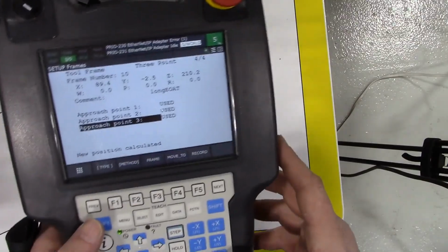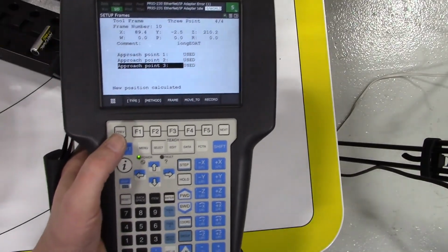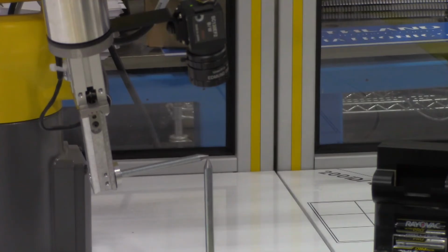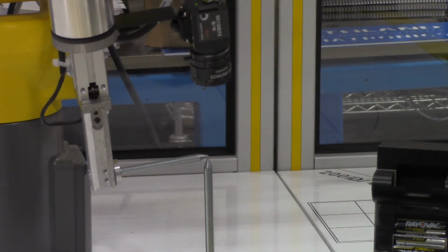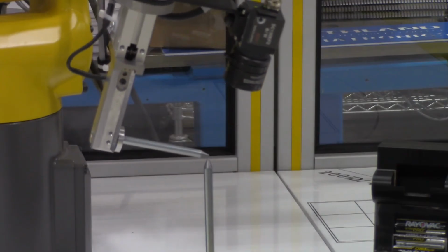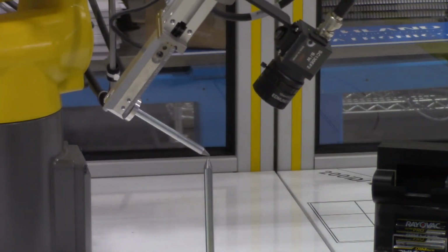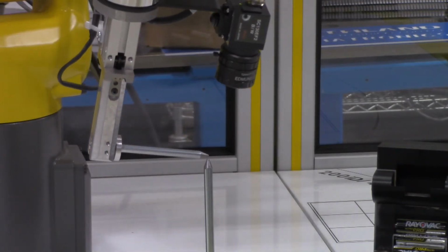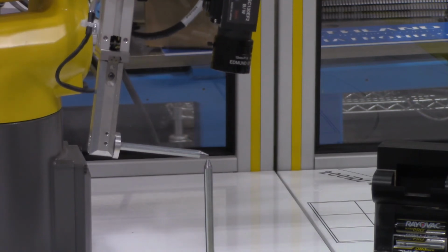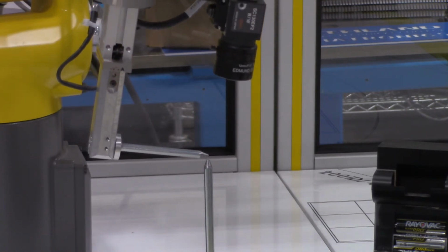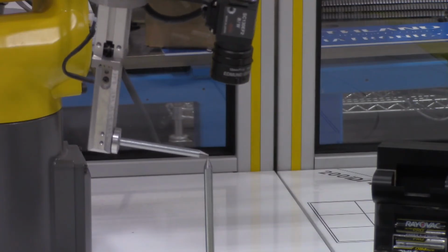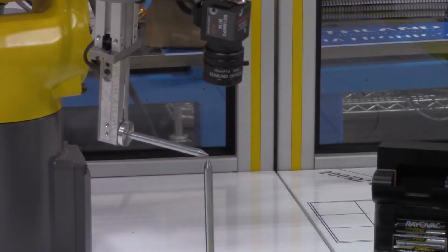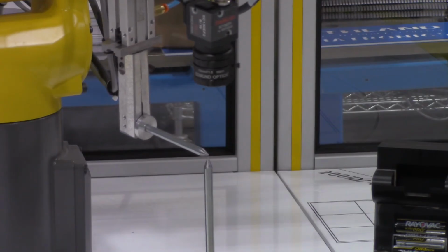Now if we did this correctly, when we jog the robot around, that new tool point should be configured. So let's see if it is working properly. And to test it, all we have to do is rotate about the minor axes of the robot. So here's an X rotation. Look at that. Thing of beauty right there. Here's a Y rotation. And again, those 2 points are pretty much sticking to one another in space. And a Z-axis rotation. That is very, very cool to watch.